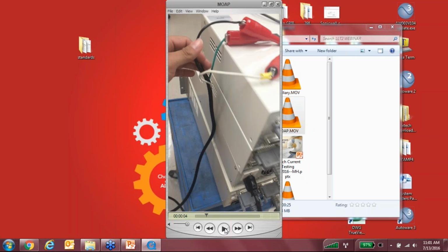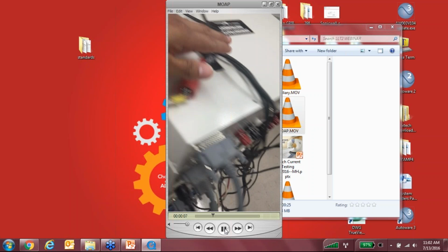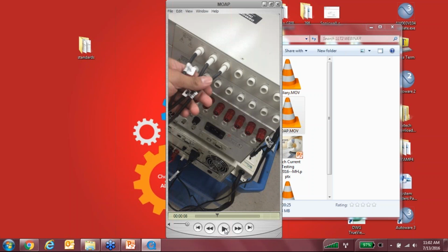And I've attached an alligator clip to each of those isolated lines. Because, again, as we looked at the diagram, I'm only sending one of those to my measuring device. So those alligator clips, I've got them going to three distinct channels on my scanner, right?